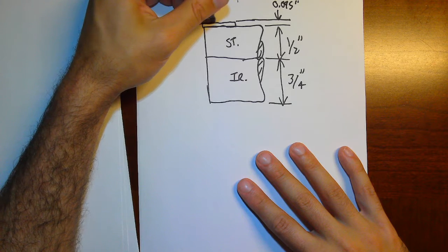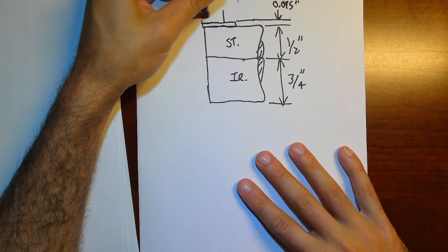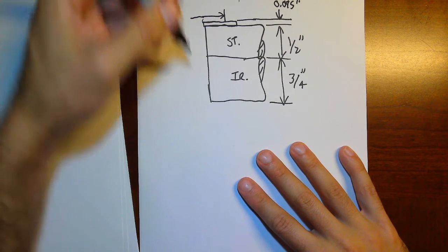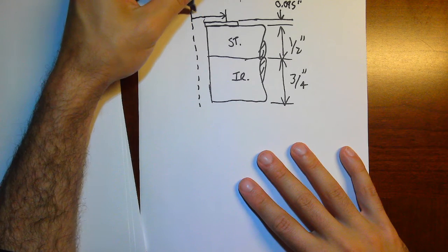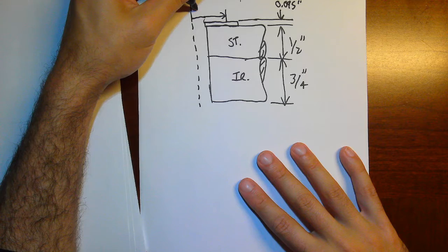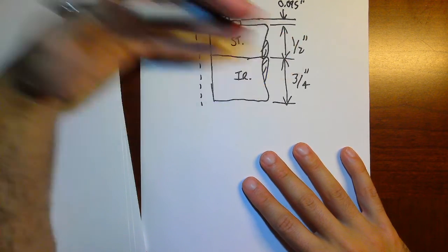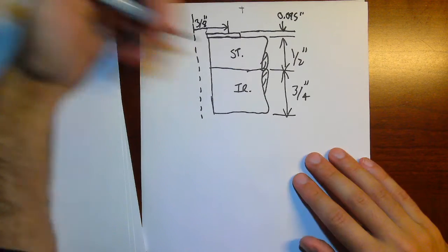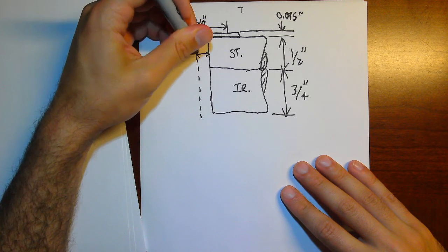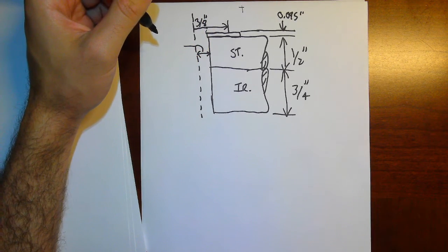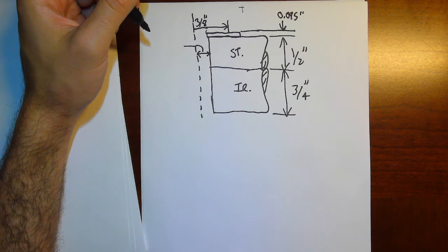I know that my stress distribution starts at a point that is a measure to the center of this hole, it's 3/8 of an inch from the center of the hole, because the whole head of the bolt is 3/4 of an inch wide, so half of that is 3/8. This hole, well, it's nominally a ½ inch, right? Because that's how big the bolt is.